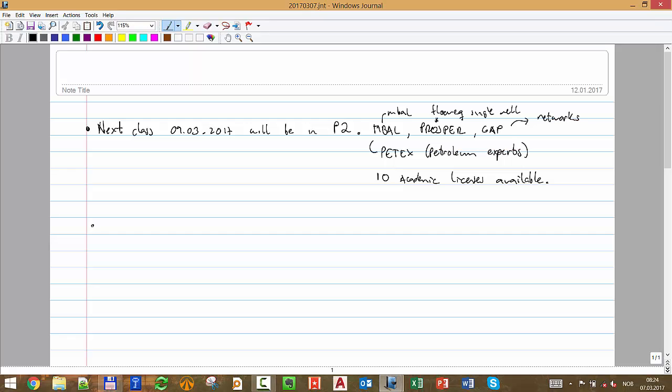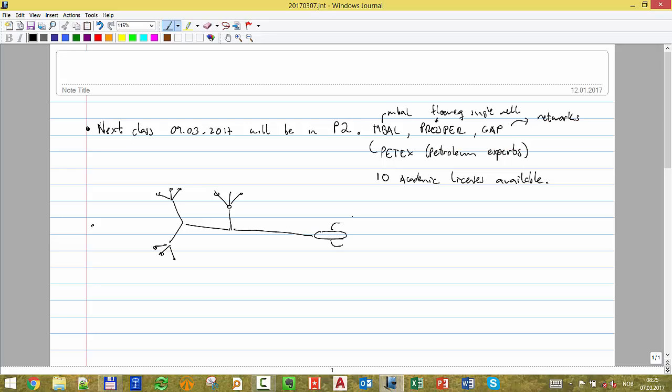So you saw with networks that we have to solve for flow equilibrium, which is much more challenging because you have many branches and many junctions if you have a very complex network, and groups of wells. These networks might be in the order of just a few wells, maybe 4, and can go all the way to 600, 1,000 wells, and then it becomes very complex. This process of solving networks becomes very time consuming. But no matter how you solve it, and there are many ways, it's just a system of equations that you have to solve at the end.